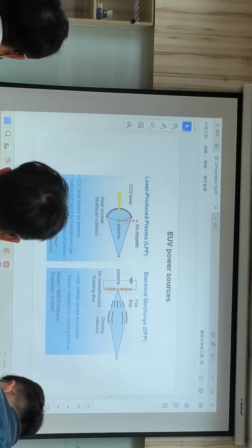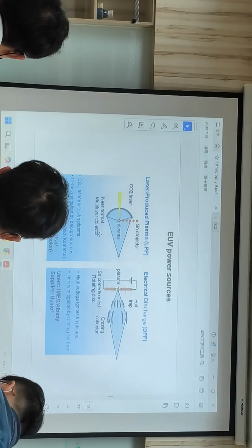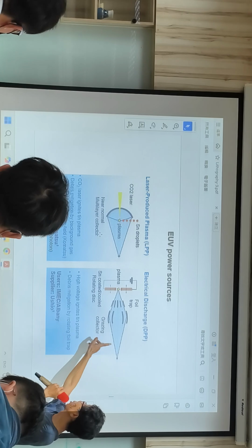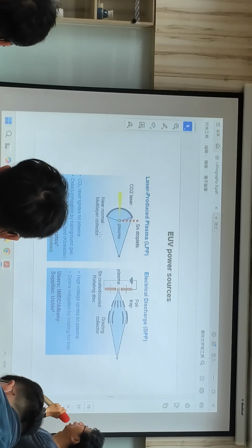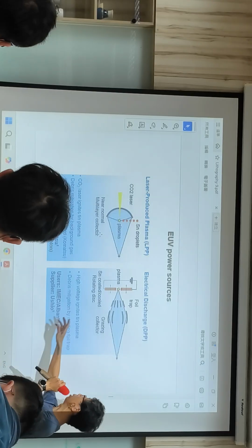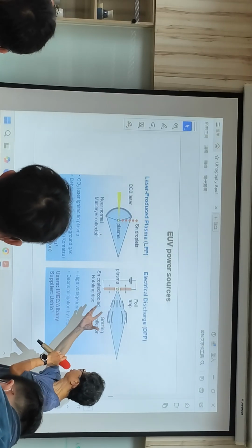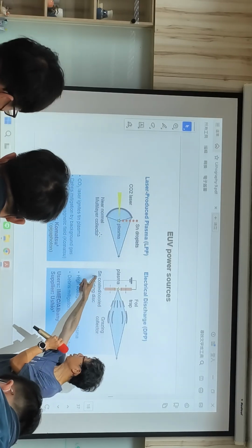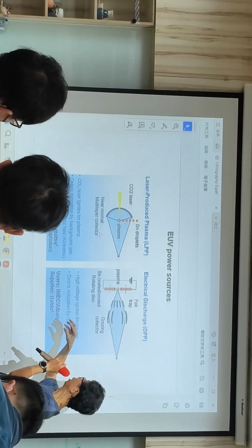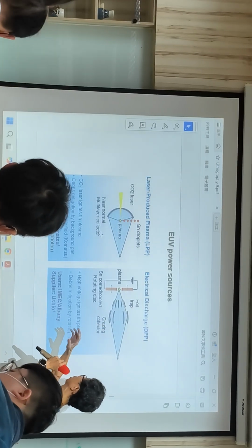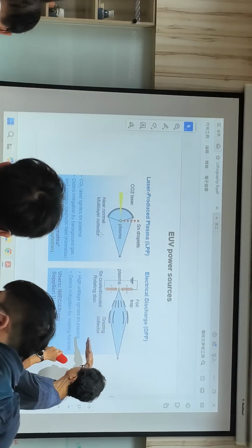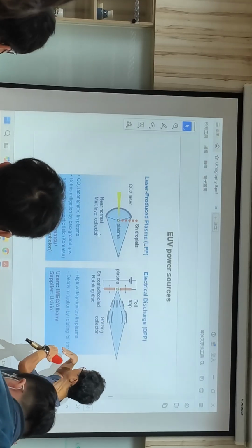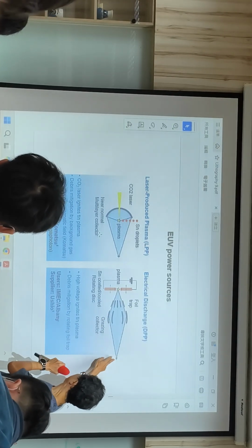Okay. And EUV power source. Initially, there were 2 competitors. One is called DPP, one is called LPP. And DPP was using plasma to arc. Okay, so this is a tin. Sn stands for tin coated, and it is a rotational disc. And the light goes through here, and then it is a foil, and the light kind of glazes through all these mirrors before they arrive.